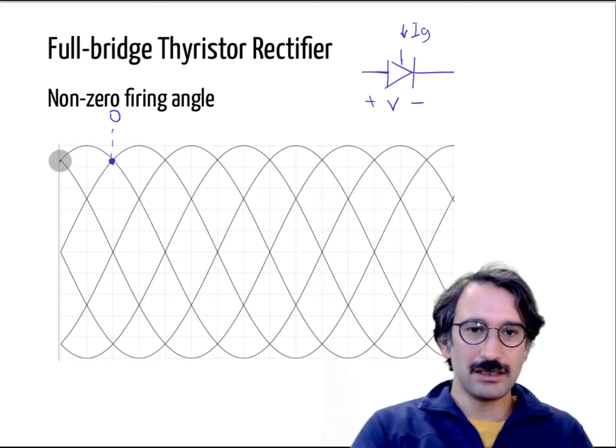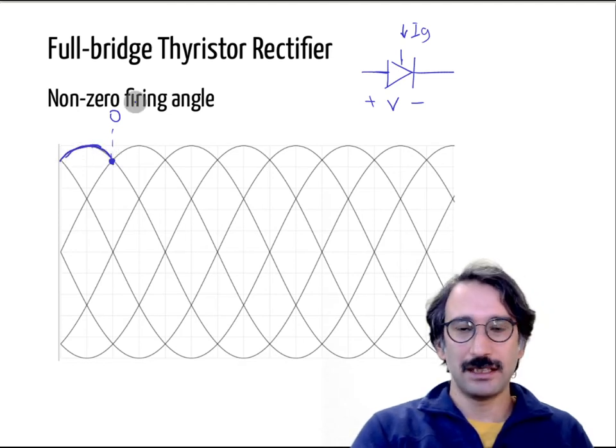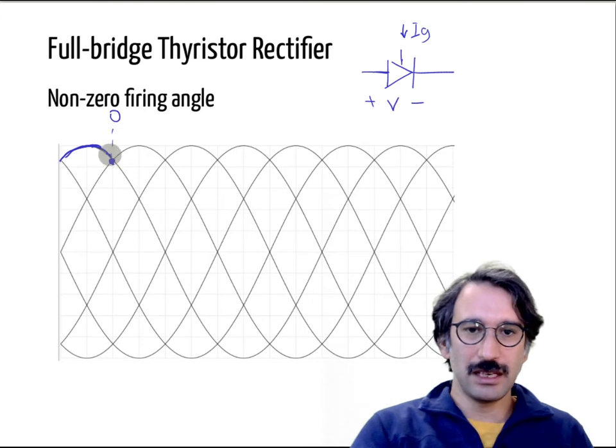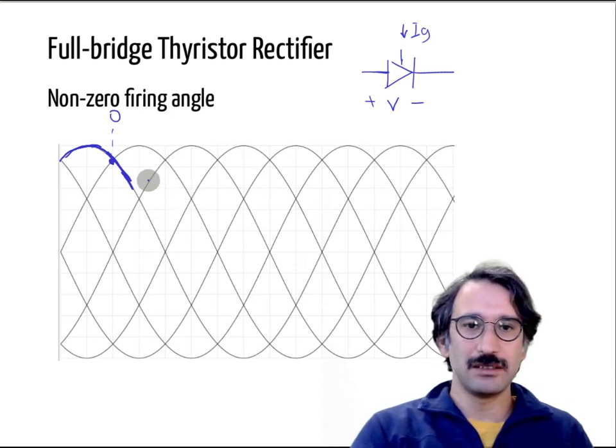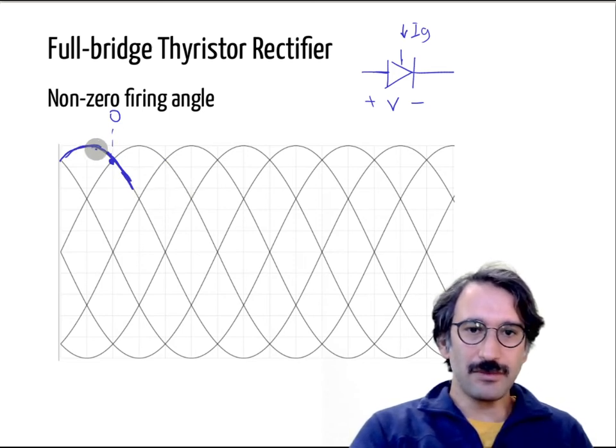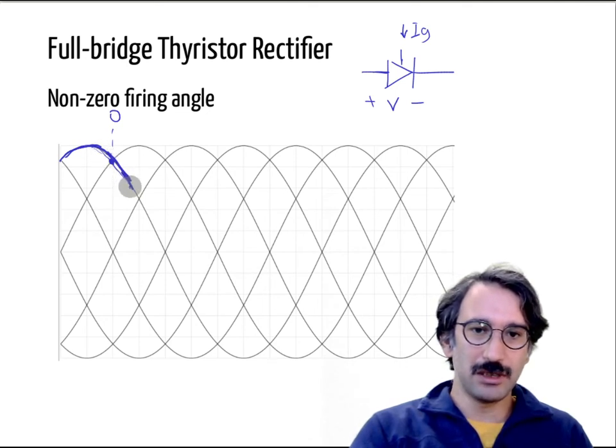If it doesn't get into conduction, but we have an ideal current source, it has to carry that current, so we will still have the same configuration for some time. It's like the single phase diode rectifier, but now it's like the single phase thyristor rectifier, but now we are following the line to line voltages.